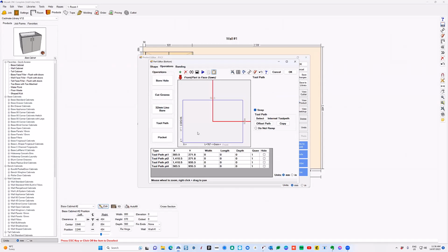We'll paste that in. Now, if you're going to copy and paste between, it's important that you use the formula control rather than the anchoring. So I wanted to show you the difference of this. So it's pasted the exact same size option, and it starts with the first lower left corner to the middle of the product. That's what happens when you don't have any formula control over it. So your anchoring is only relative to the part that you started it on.